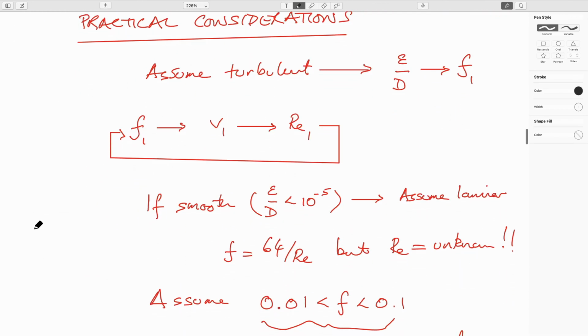So what we've done, if you look at it from 35,000 feet, is we've chosen a friction factor based on, in this case, our roughness. We've chosen the first friction factor. We've used that friction factor to calculate initial velocity from h_L equals friction factor times length over diameter times V squared over 2g, rearranged in terms of velocity, right? This term here.